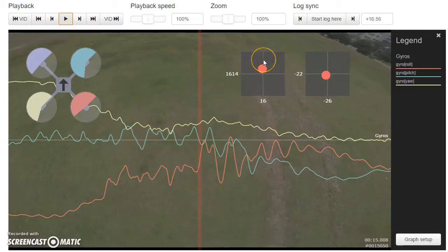So in general, my philosophy is that wherever my throttle is normally at when I'm cruising, I want my TPA breakpoint to be about there or maybe a little higher. And I don't want to be setting my TPA breakpoint down here and then having to tune TPA and my PIDs here. There's no sense tuning for a low throttle position if you're never really going to be there. So tune your base PIDs for wherever you're normally cruising, and then if you need to, add TPA to lower them as the throttle gets higher.